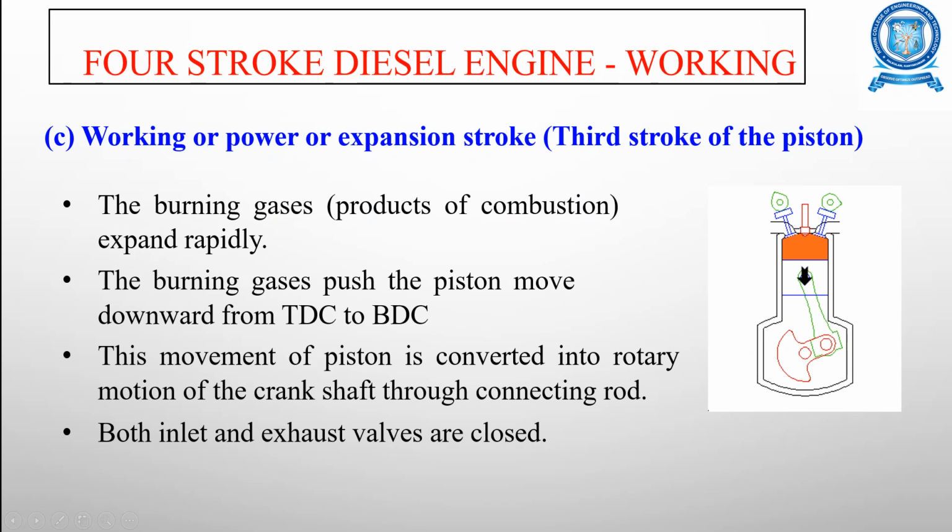As a result, the piston is moved downwards under great pressure, and hence the piston moves from the top dead center towards the bottom dead center. This movement of the piston is converted into the rotary motion of the crankshaft through the connecting rod. Both the inlet and the exhaust valve remain closed.